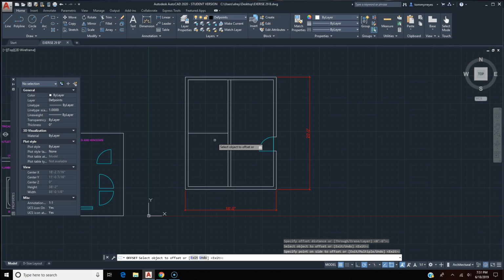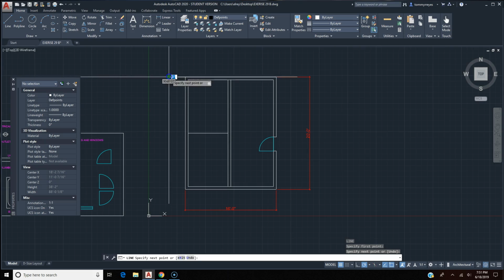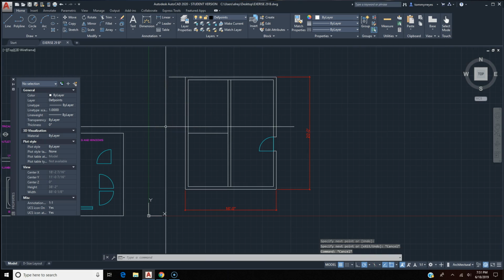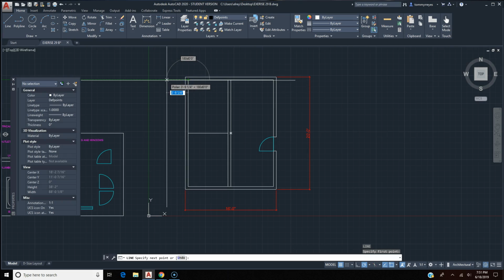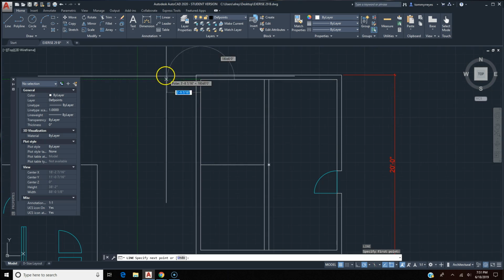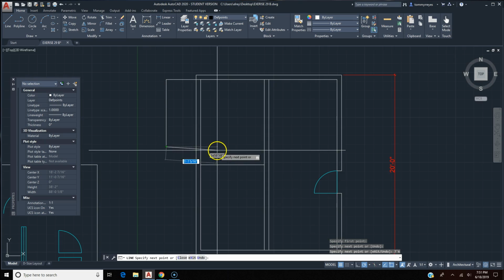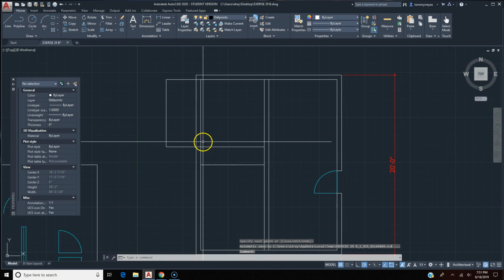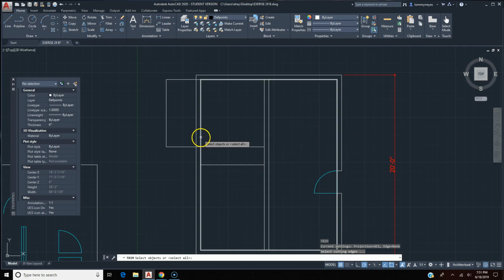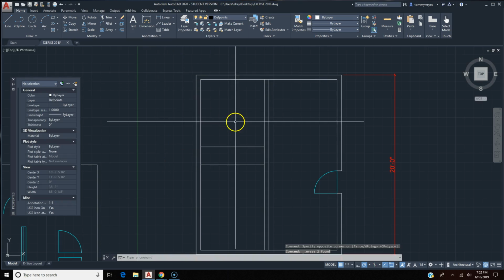So this line right here, I'm gonna make some construction lines. So I'm gonna go here and, oops, not there. Delete. I'm gonna go here from the inside of the wall, because that's what the measurement is, and down 7 feet 6 inches, and then I'm just gonna go over. And now I'm just going to trim. I'm going to trim from here and then just delete these construction lines.